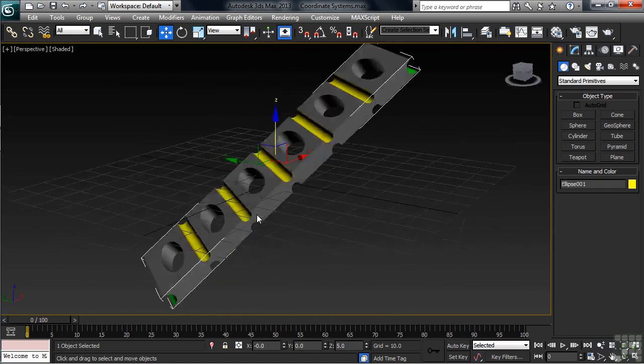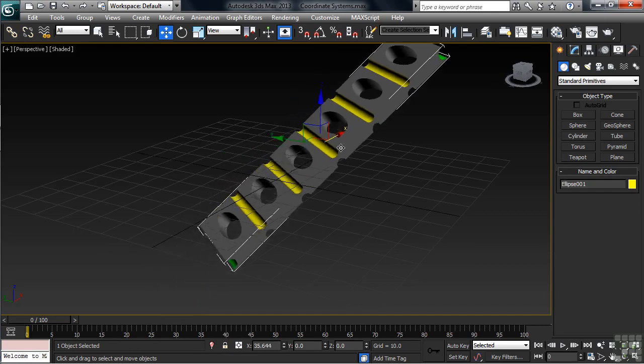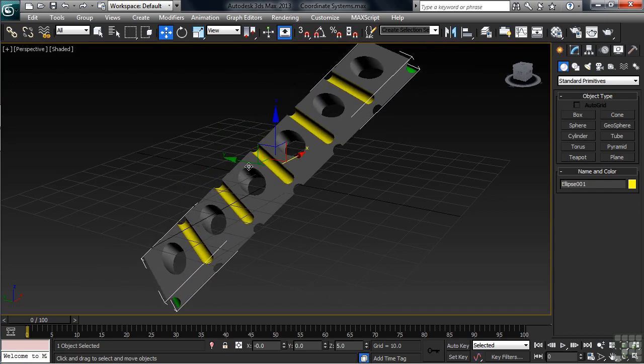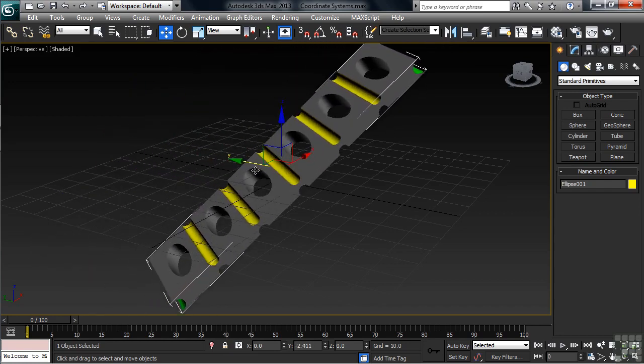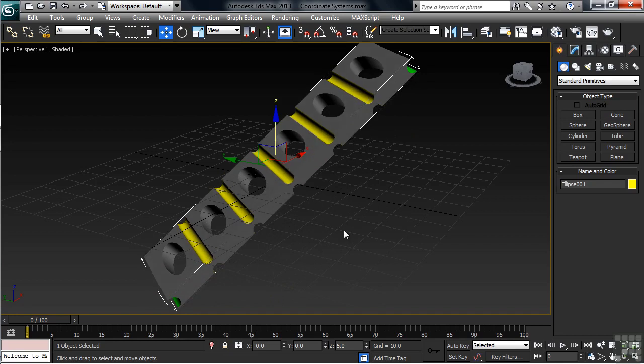Notice how the gizmo sticks no longer point in relation to the orientation of the object. They instead, as usual, point in the direction of the grid, the world coordinates in other words. And that now creates a problem if we want to move the object in its own direction. Let's try each, red, green, and blue, and you'll see what I mean. In order to have the ability to move in relation to the object and not in relation to the grid or the world in other words, we need to switch to using the object's local coordinates. Here's how you do that.